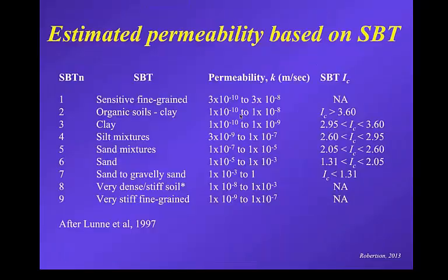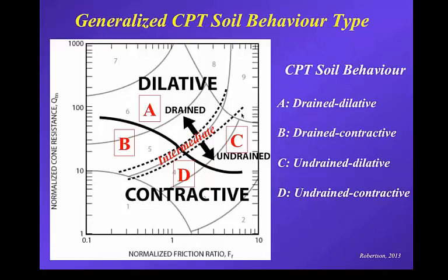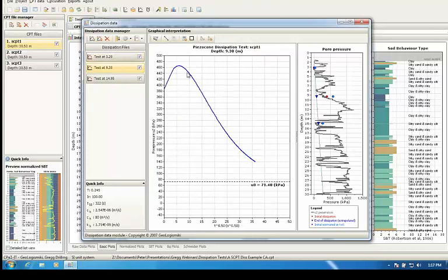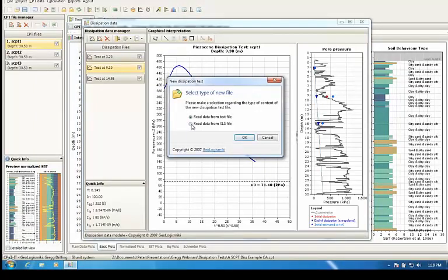Well, in general, if it's a contractive type soil, pore pressures are going to be positive, and you're going to get the types of dissipation, the monotonic ones, particularly if it's highly contractive. But it depends on the pore pressure location. I'm assuming the question is the more typical U2 location. And so if it is a contractive soil, you'll typically see close to a monotonic dissipation. Although, as you saw here, the soil was lightly over-consolidated, so it did rise before it dropped. Next question.